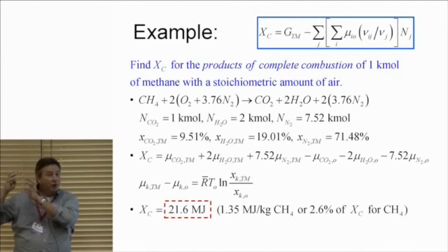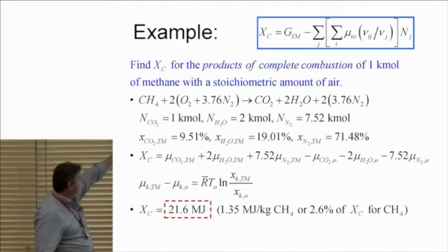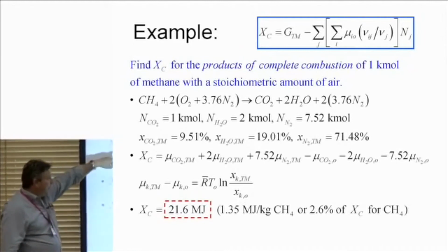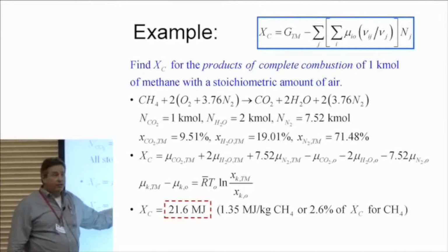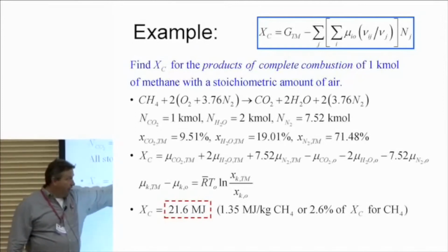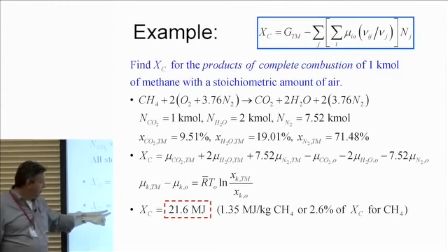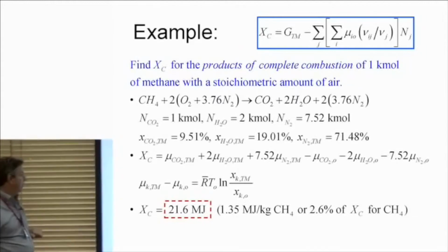We may think this is small, but is this starting to sound important to you? My resource, 1 kilomole, no chemical reaction required. It's delta mu between the CO2 state and the environmental state. I can write that in terms of the mole fraction, 19.6 megajoules.